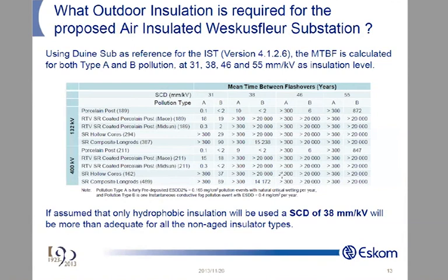If it's conductive, it's tracking. If it's not conductive, it's erosion. Normally silicon has problems because of its composition and material structure; normally the silicons erode. But I didn't diversify too much, so I'm not answering your question.